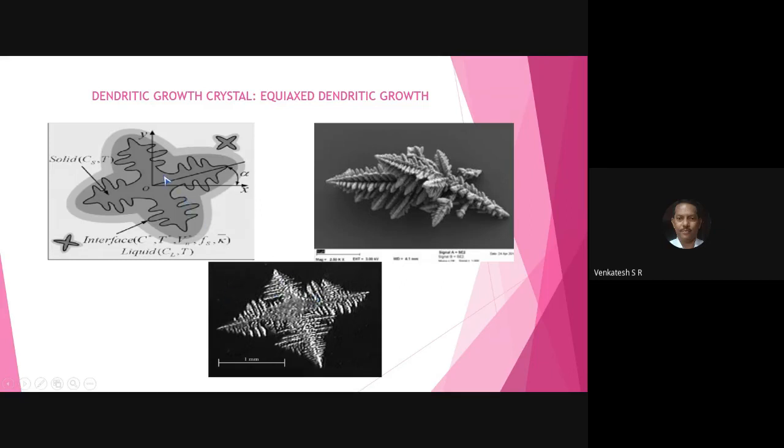All of you observe here. The crystal grows in size in two directions, that is X and that is Y. And this is the angle, the critical size of the nuclei. This is the critical angle at which the crystal grows in size, attracting the neighbor nuclei, and the angle is alpha. Please write down: dendritic growth of crystal, colon, equiaxed dendritic growth. This is very, very important.